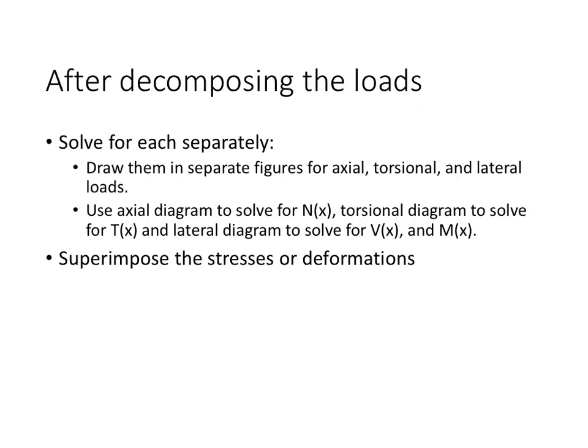So after decomposing these loads, the next part of the process to solve problems with combined loads is to solve the problems separately. So we can draw separate figures as axial, torsional, and lateral loads, and then we can use each of these to solve using free body diagrams for the internal loads. And once we've done that and solved the problems, we can calculate stress and deformations due to each type, and we can superimpose them. And this is covered in the next video. Thank you.